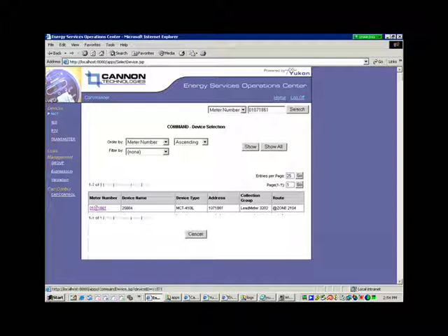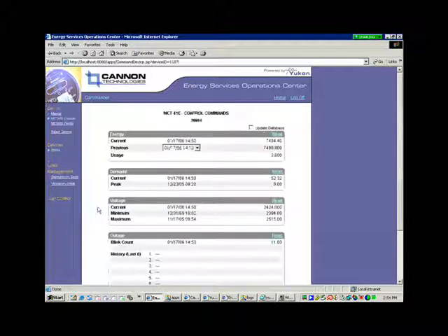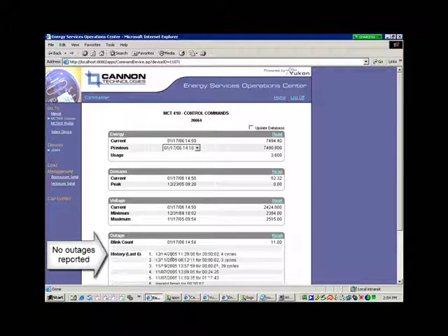Since a customer call was received by the Milsoft's dispatch system, and the outage verification performed using the Multispeak interface verified that the meter had power, we can view the AMR meter's internal outage log file to verify if the meter did in fact not lose power. This meter does not have a recent outage logged, therefore the outage is at the customer's breaker or fuse. The combination of outage analysis and AMR using the new Multispeak version 3 web service interfaces gives dispatchers the capability to be more responsive and proactive to outage events.